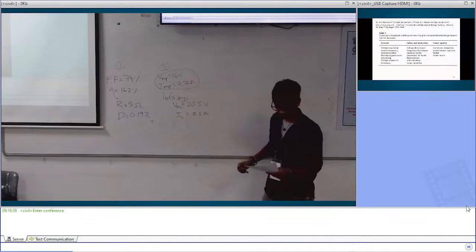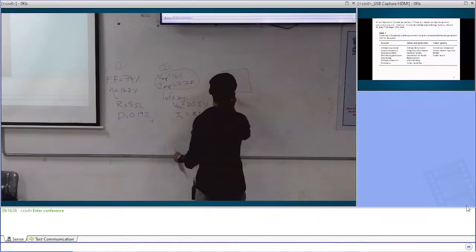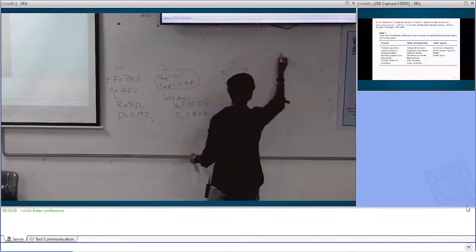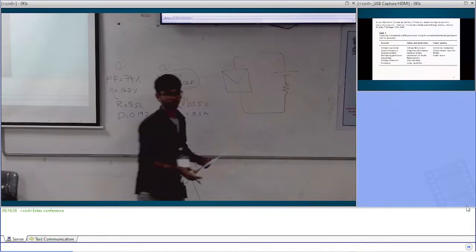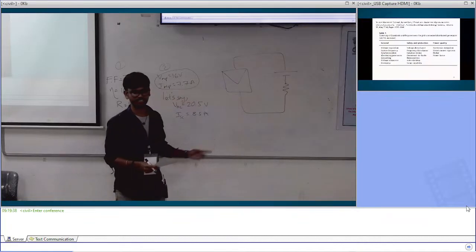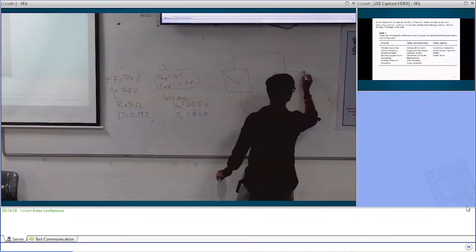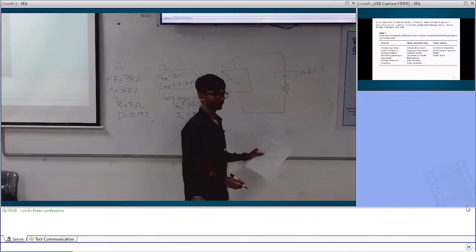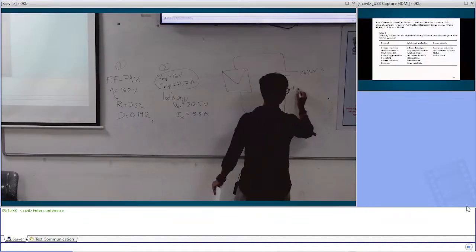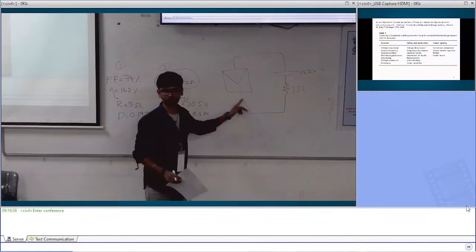So the next part of the question, when the battery is connected across the panel. We have been told that a battery is connected across the PV panel with open circuit voltage of 13.2 volts and internal resistance of 1 ohm. At this condition, we don't know the operating point of the PV.